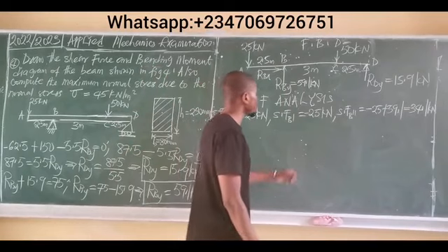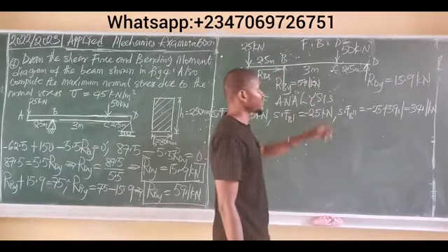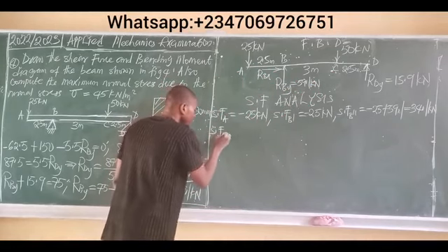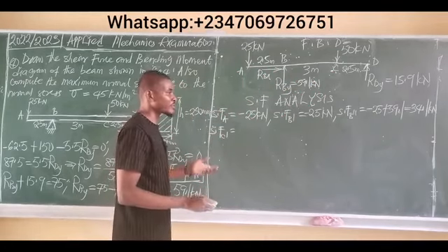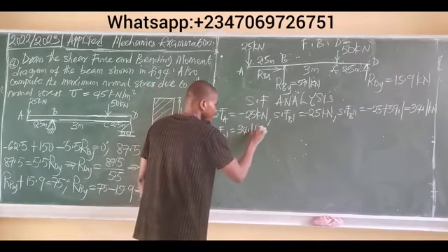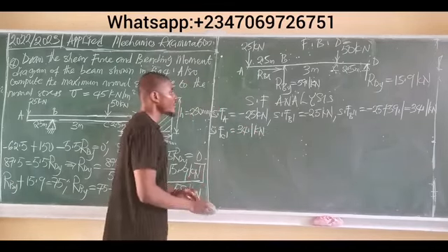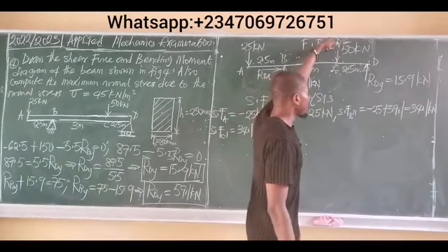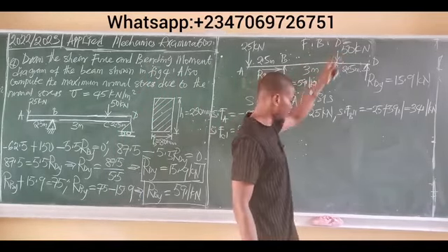Now, this same force moves from point B down to point C initially. So you indicate that as shear force C prime, which means initially at point C, this same force, 34.1 kilonewtons, exists there. But on getting to point C, this force now encounters a downward force of 50 kilonewtons.